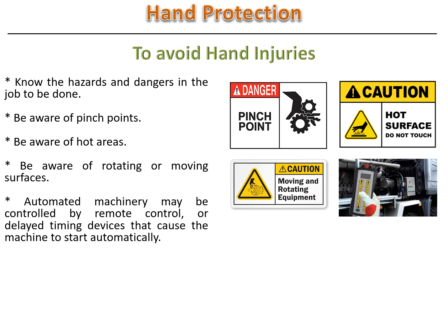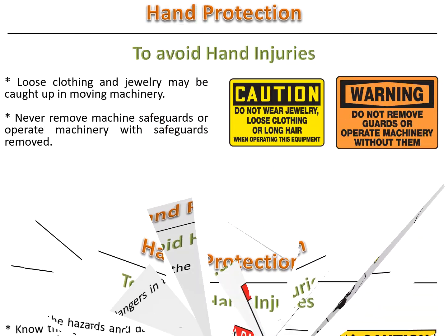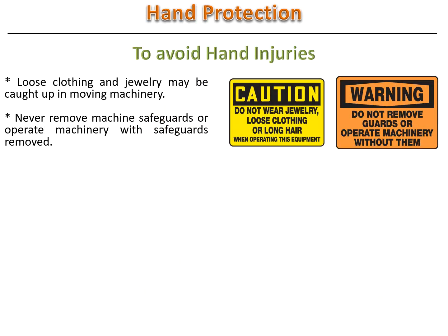Automated machinery may be controlled by remote control, or delayed timing devices that cause the machine to start automatically. Loose clothing and jewelry may be caught up in moving machinery. Never remove machine safeguards or operate machinery with safeguards removed.